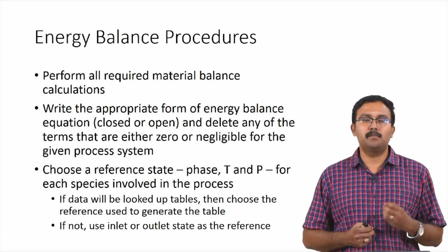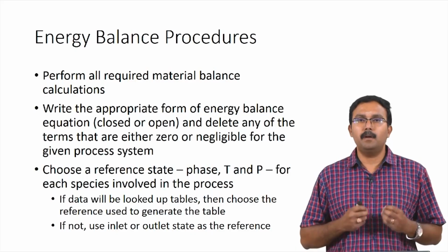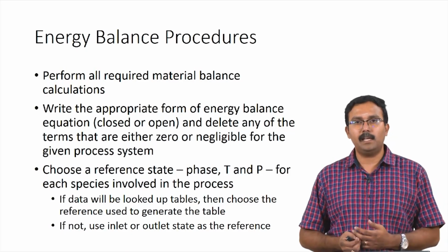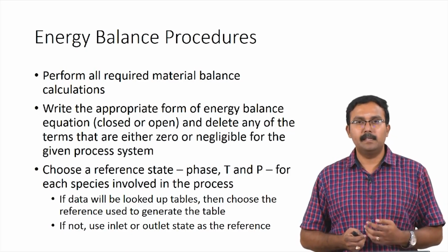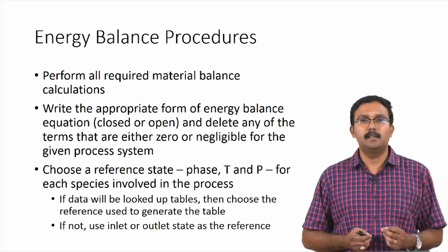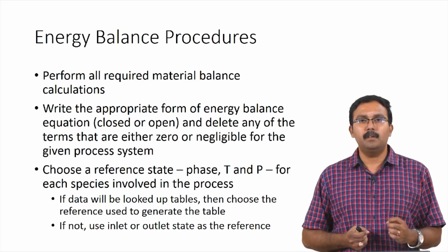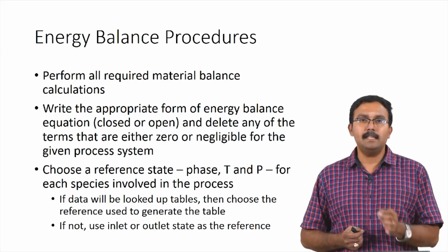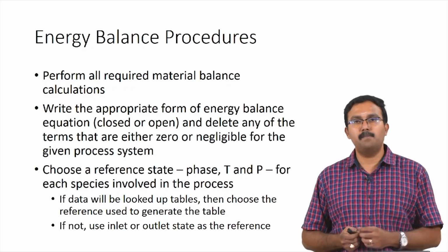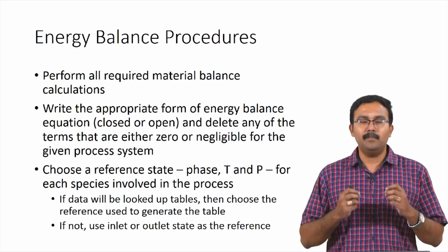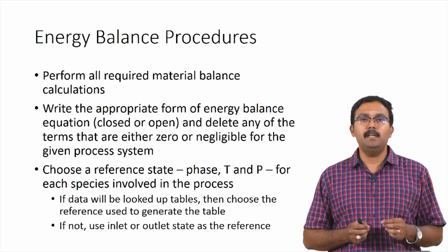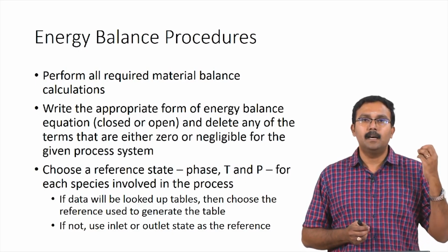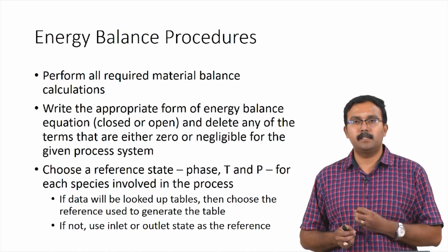You would have to choose something called a reference state. While we performed material balances, we always used a basis. So, based on the basis we performed all the calculations. When we perform energy balances, it is important to choose a reference state, because if you remember, we mentioned this in earlier lectures, enthalpy and internal energy changes can be measured. However, we cannot measure the absolute values. So, this means whatever calculations you are performing would have to be in reference to a reference condition. So, the reference state will be defined as a particular phase, temperature and pressure.